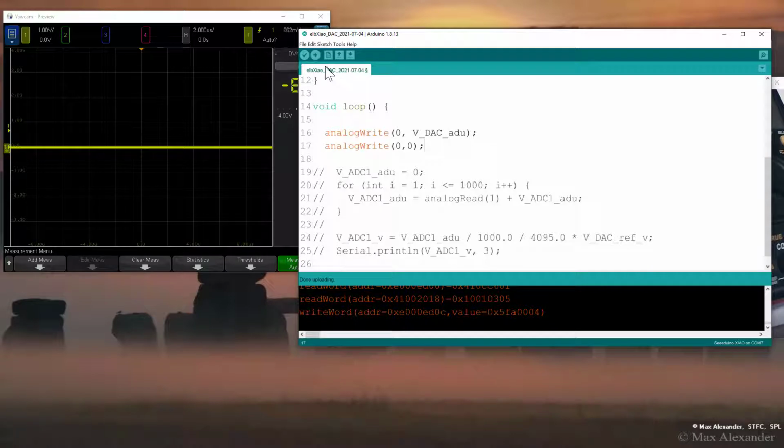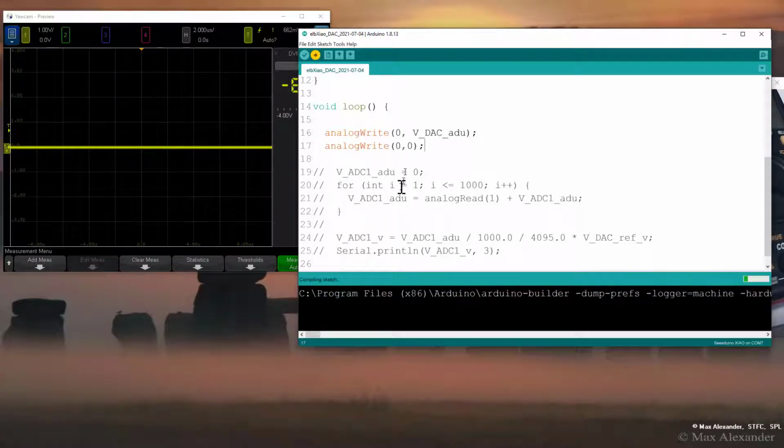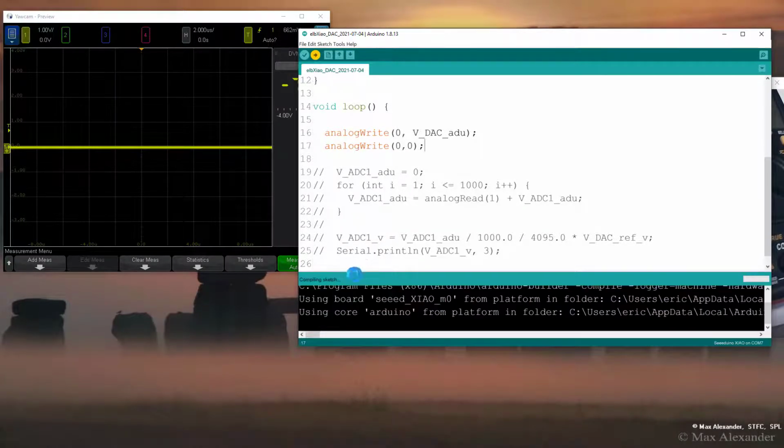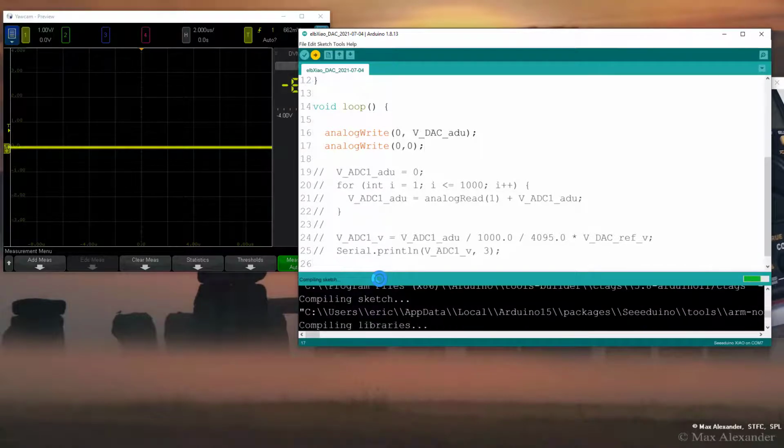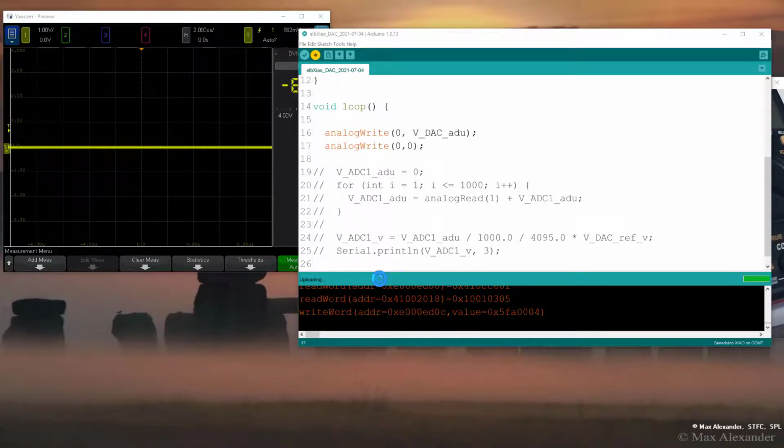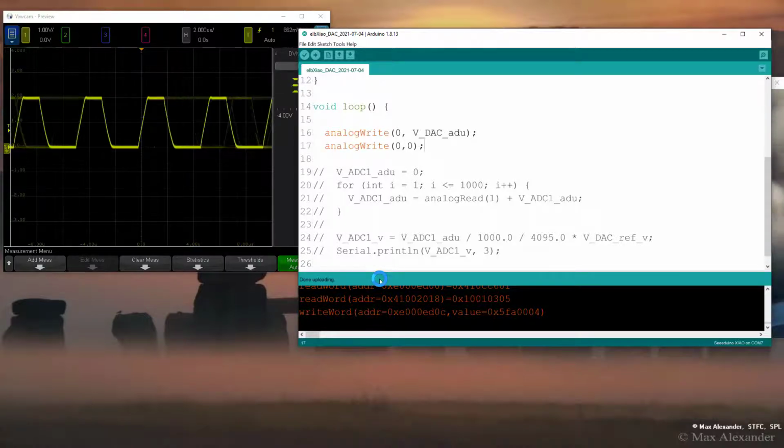it a little bit. So let's upload the code, say compile, and we'll get the upload, and it's done uploading. And now if we look at that analog voltage coming out, we ought to see a nice analog voltage. And let's see. Hey, there we go. And you can see on the scope, nice analog voltage. It's that square wave. Well, not quite a square wave because there's a finite slew rate for the DAC.